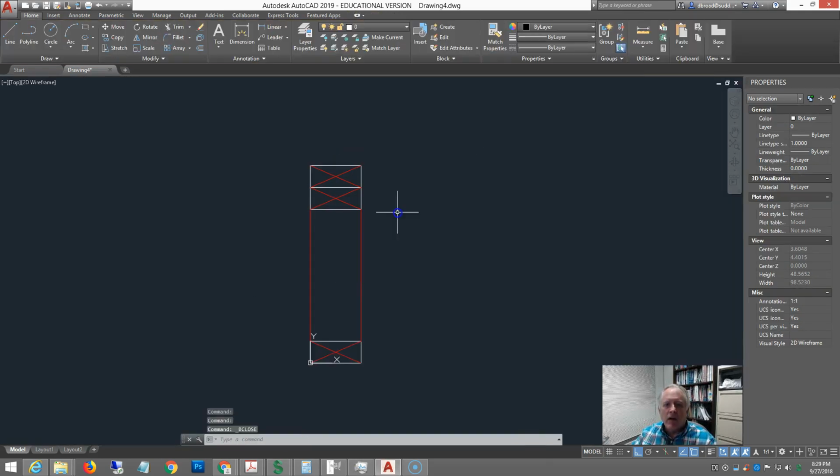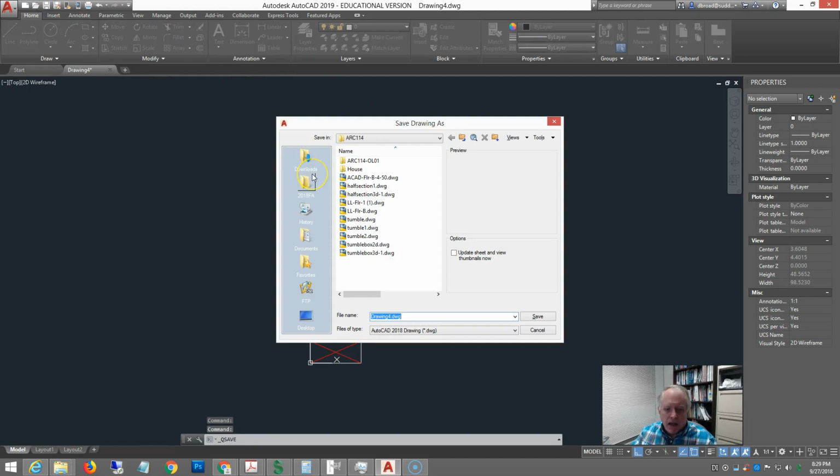Save the current drawing. This does not save the drawing to a file. It just saves the state of the current drawing, so it remembers all those block parameter settings. Now we need to save it to file. So go ahead and push save and give it a name that you can remember, or maybe studs or stud section, so you know what it looks like.